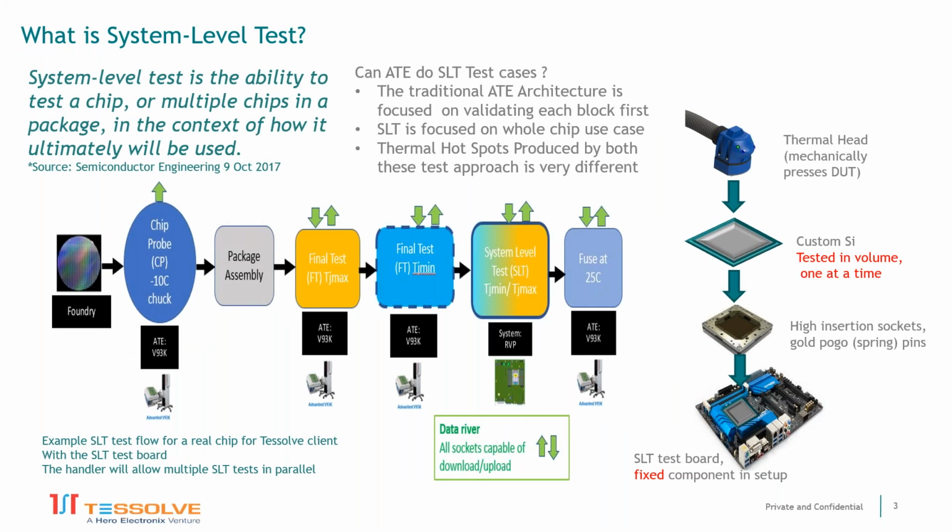So here, what we're trying to show is what the normal chip test is. This is looking for production faults rather than functional faults. So this is a production test flow. Normally, you can do a wafer level test using probes. And then when you cut and dice the individual chips, you can package them and then do a final test.